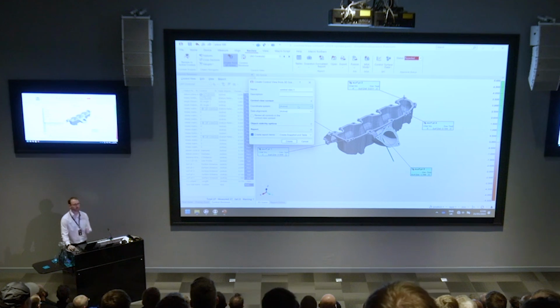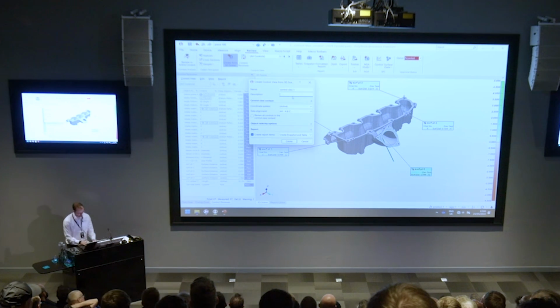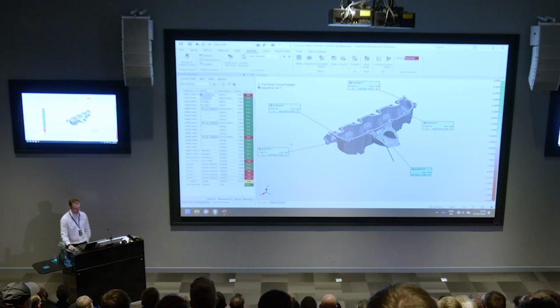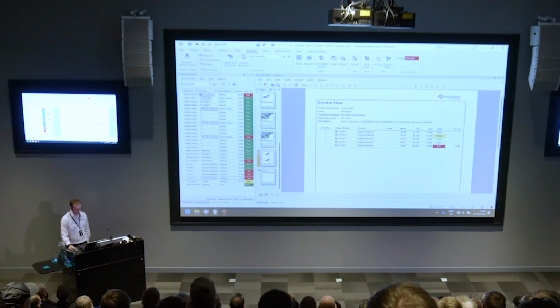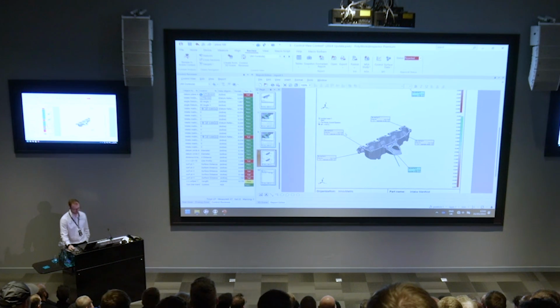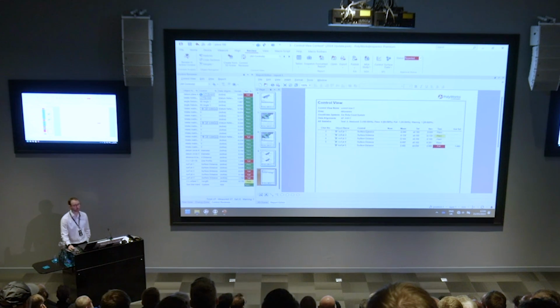So this is effectively the same now as when you went into your snapshot and tables and changed the context for the properties. So if I set that to DRF ABC, I'll just add that to my description as well. So DRF. If I now hit create, effectively in my report, because of how this is set up, you will now see at the bottom of the report, we now have an image specifying ABC, and also the table as well.